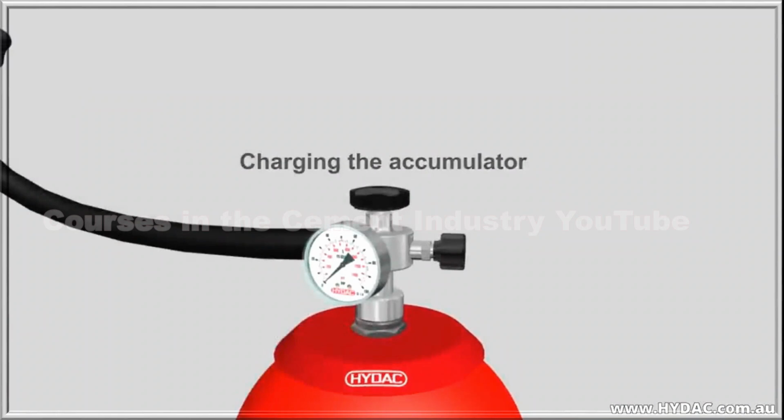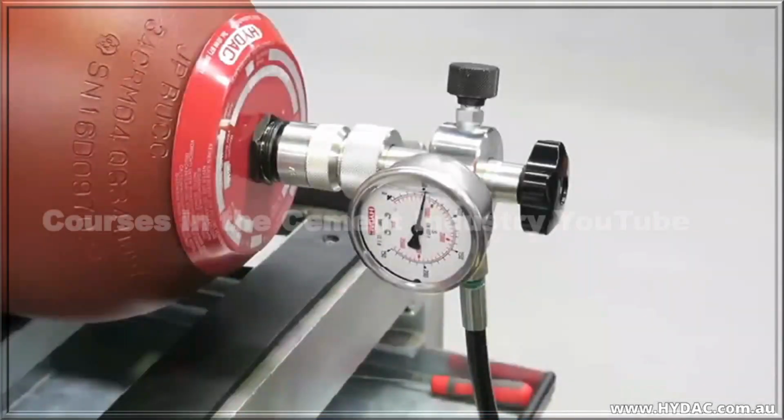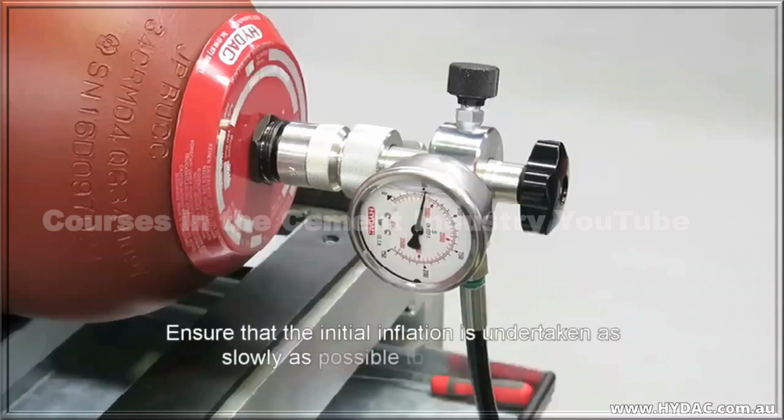When shipped, the majority of HYDAC bladder accumulators are charged to 2 bar. At this pressure, the bladder is inflated and is in contact with the inside of the shell, and there is little chance of damaging the bladder. However, if the bladder is new or has been deflated, you must ensure that the initial inflation is undertaken as slowly as possible, otherwise the bladder may stretch too quickly and rupture.